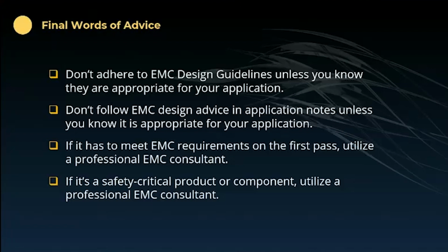And also, if it's a safety critical product or component, I would highly recommend that you get somebody who's basically an expert in EMC to help out. If you take that into the test lab and you modify it to the point where you pass the test, you've got a product that will pass that test in that lab. You haven't got a product that's going to work reliably in a system. And if it's safety critical, you really shouldn't be designing your products that way.